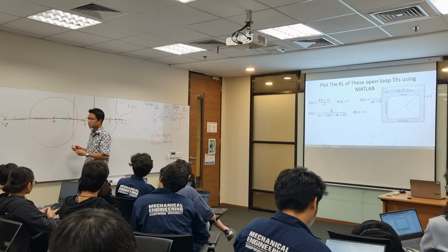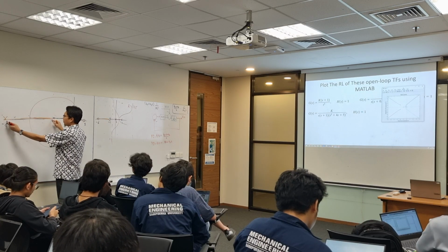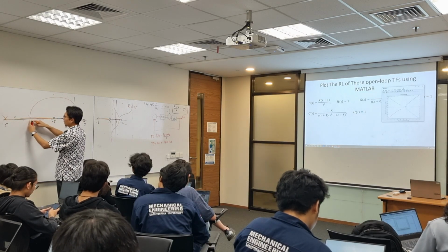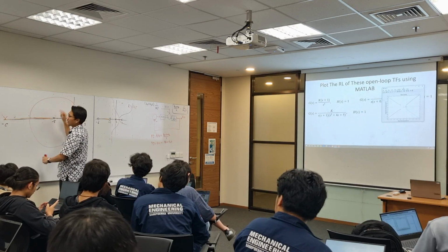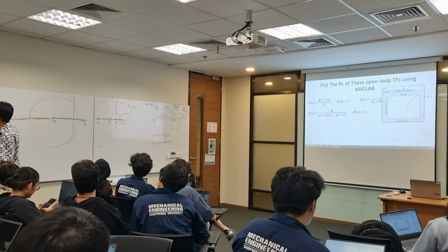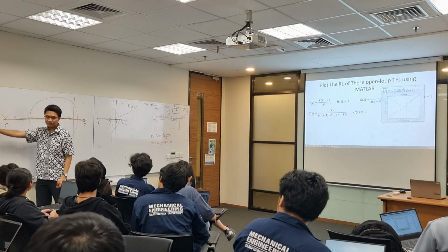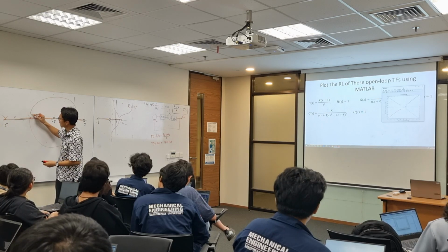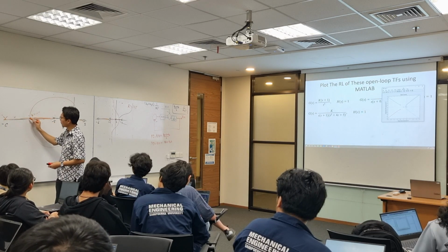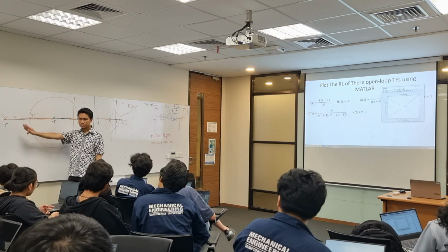What's good about this is that the root locus will go here, and all of them will break like that. I can push this more to the left, so that this point will be far more to the left. So I will have k equal to something where the open loop pole is much faster than -5. I can do that.